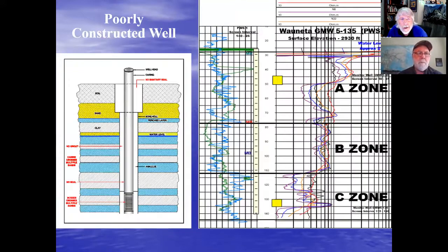And what we found through the initial phase of looking at the existing well construction was poorly constructed wells. As this schematic on the left shows, the design was to have the screen down here in the lower horizon, but in essence, not only did the screen cross multiple aquifer horizons, there was no annular seal screening off the shallower aquifers. So basically, you had a fully commingled well out here.